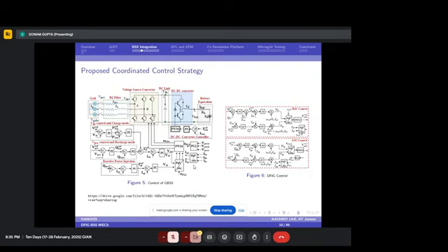And similarly, there is the control of the grid battery storage system. Here we are mainly focusing on the line side converter control and the rotor side converter control of the DFIG. In the line side control, we can see the reactive power control is also there, which also depends upon the change in the voltage at the point of common coupling.